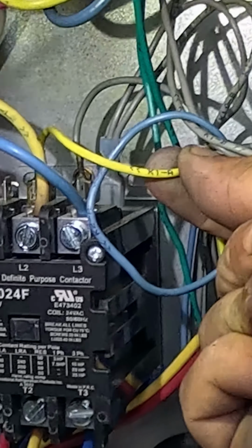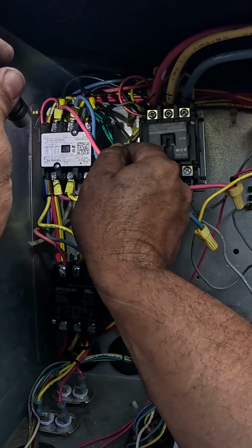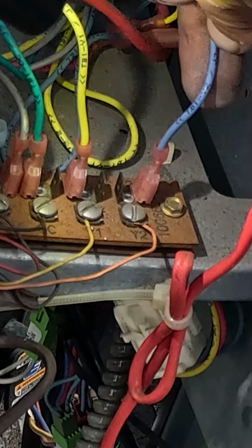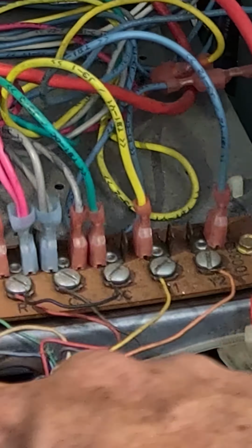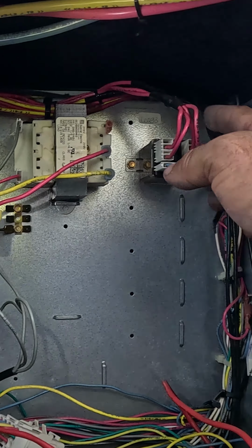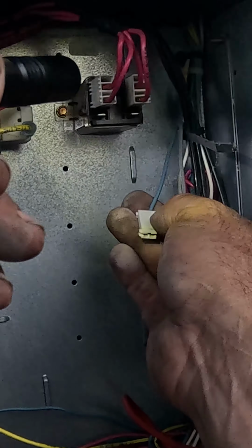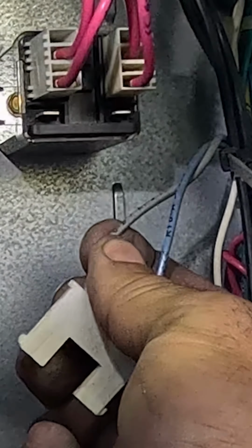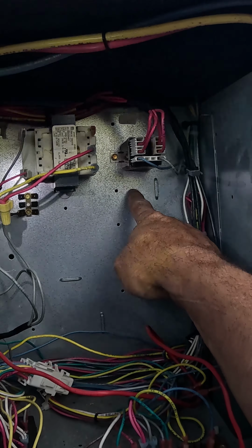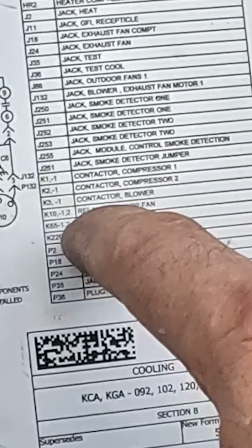This yellow wire energizing K1 is labeled K1. The green wire here is energizing what should be K2, but is labeled K3. So that's another thing you can use to try to help you. This is labeled TB1Y2. Obviously this is a terminal board and it is landed on Y2. So a lot of times the wires themselves can help you locate things. This relay right here, the wire going to the K10. Sometimes they'll have them labeled on the wall, K10, to help you out as well. But you can always go back to your key, K10, outdoor fan relay.